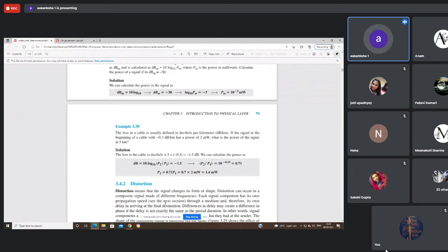A higher frequency component may be distorted more due to some distortion elements, while lower frequency components may be distorted less, or the other way around. There may be elements in the transmission medium which distort the low frequency signal but distort the high frequency signals less. So when distortion occurs, they inhibit some of the frequencies but allow some to pass through normally.